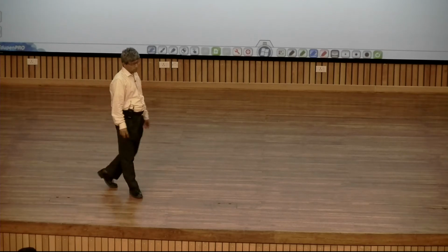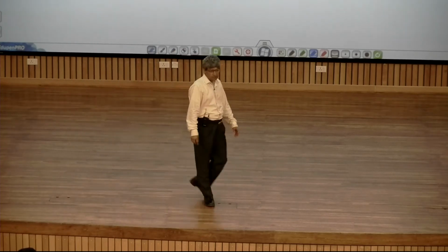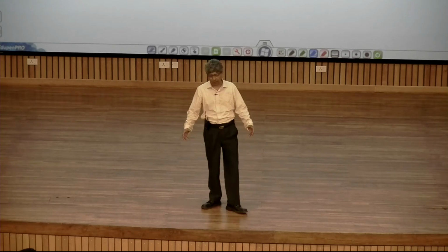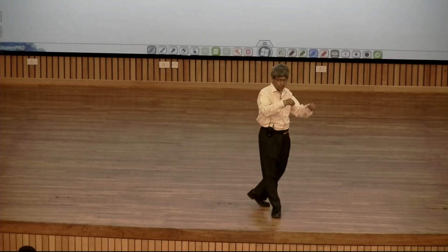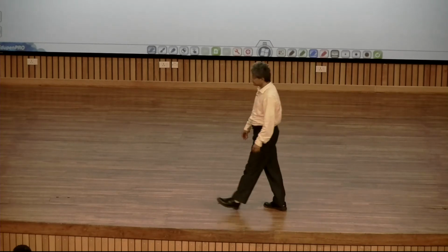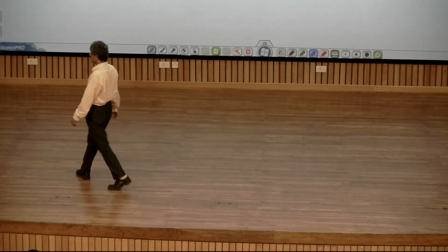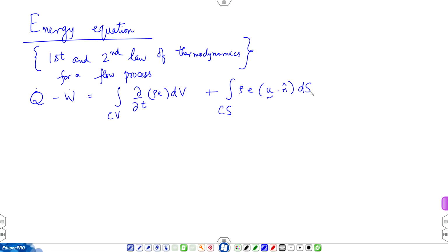It is just to maintain continuity with your free body diagram kind of mindset. So, once you become very familiar, of course, you may show reactions, this, that, all within the assembly, but it always helps if you can identify the component that is being analyzed and show the forces acting on it. So, this is a general version, but we are going to specialize to a class of problems.